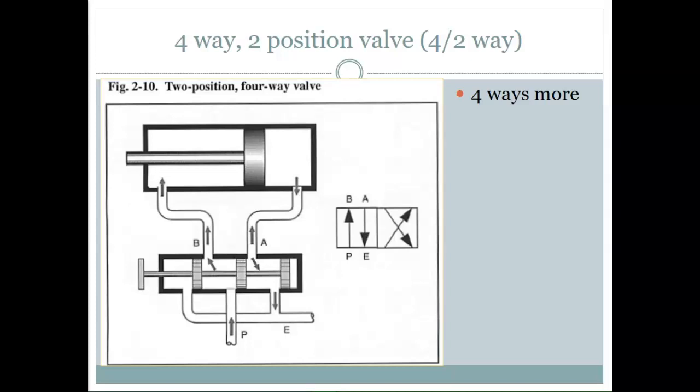So 1 will put initial pressure to 2, forcing your cylinder back. At the same time, the pressure or the air, the fluid, whatever is on the back end of this is going to be dropping down from this way to 4 and going to 3.